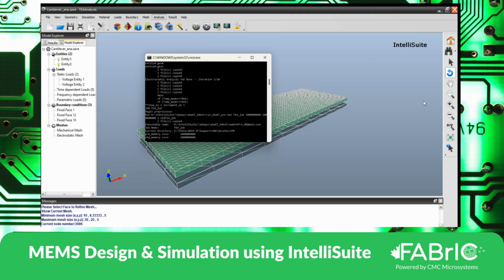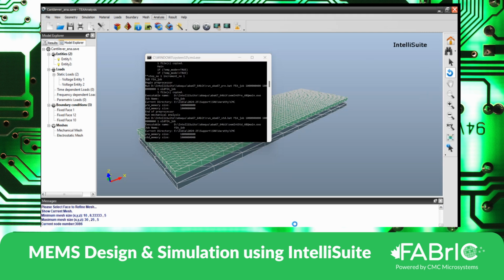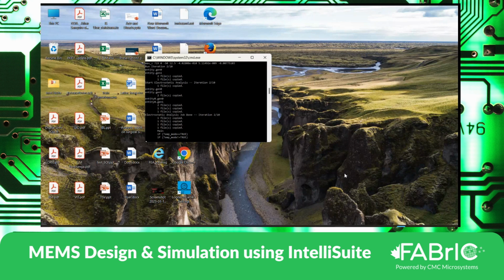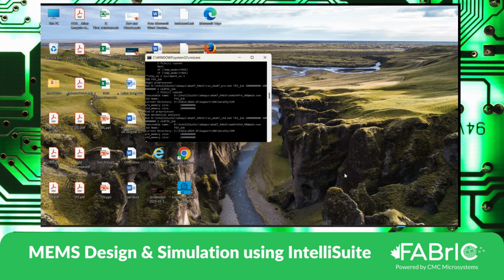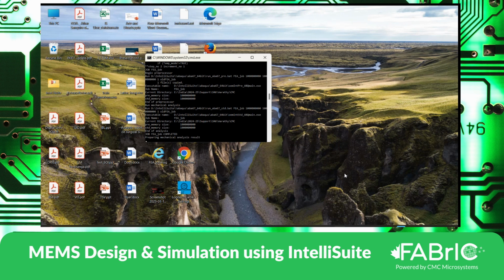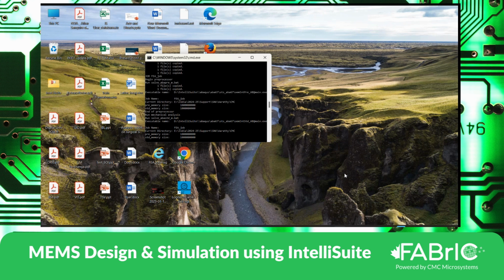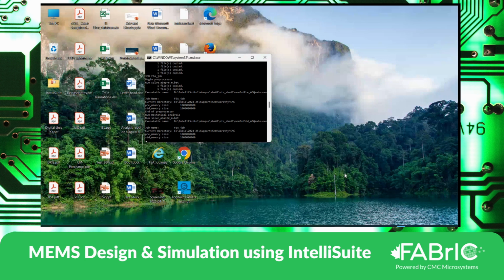And what are the different kinds of meshes that are possible through the tool? So the one we use is a 20 node brick element. Other than that, we have tetrahedral, triangular, and cubic or rectangular based elements. We have triangular specifically because sometimes the MEMS device may have curved features where a rectangular mesh wouldn't support well.